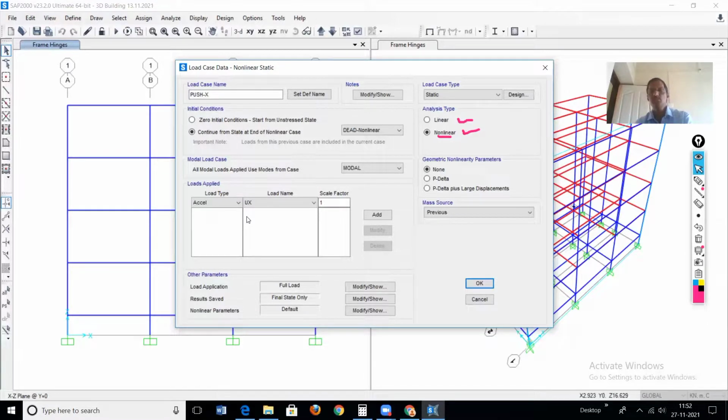First mode dominated means the mass participation in the fundamental mode in that particular direction is more than 90%. If this is the case, then go for the third option. In general, for mass participation less than 90%, the second option is also a reasonable choice. So we have selected the second.